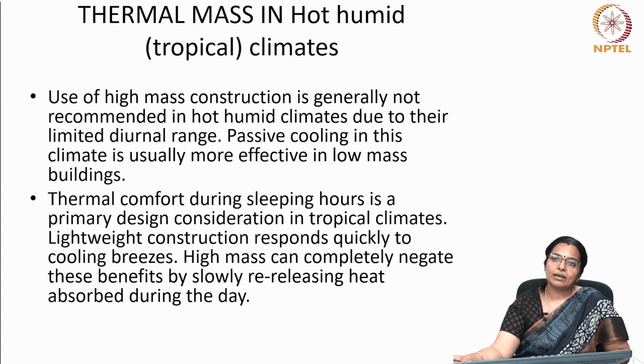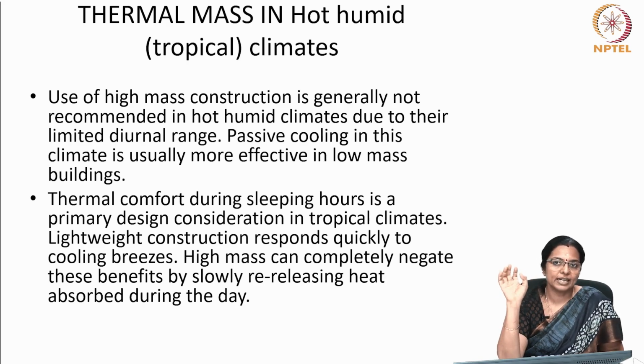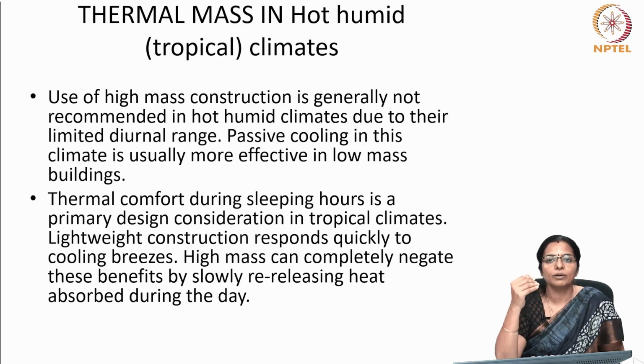So, use of high mass construction is generally not recommended in hot and humid climate due to their limited diurnal range. Passive cooling in this climate is usually more effective in low mass buildings. Thermal comfort during sleeping hours is a primary design consideration in tropical climates. Lightweight construction responds quickly to cooling breezes, and high mass can completely negate these benefits by slowly re-releasing heat absorbed during the day.